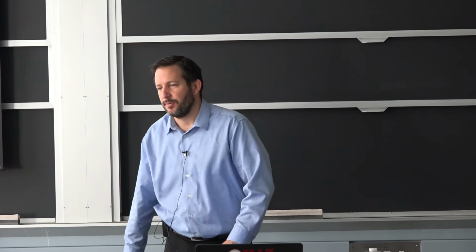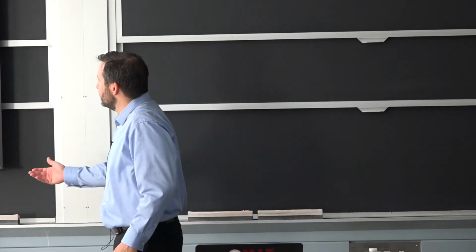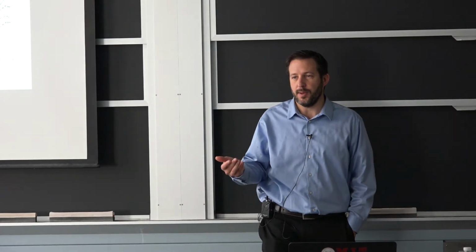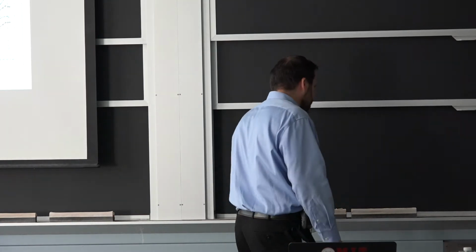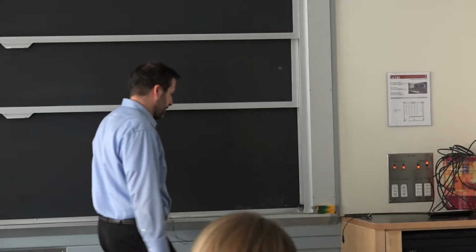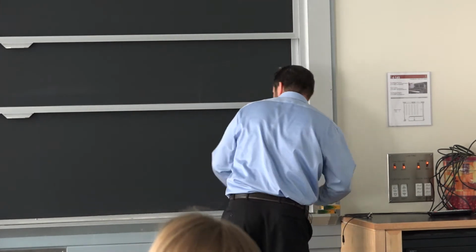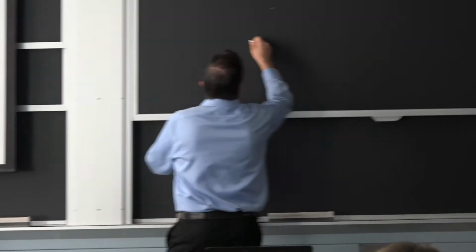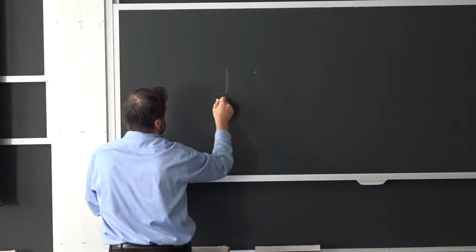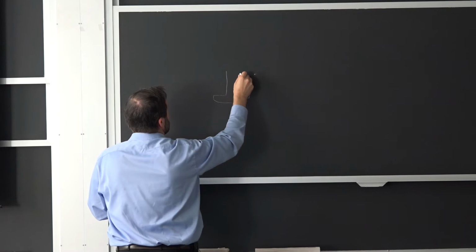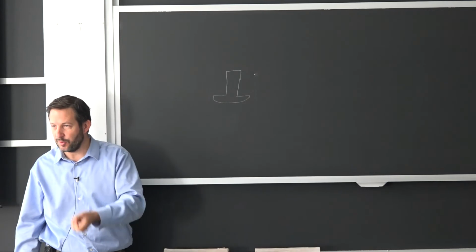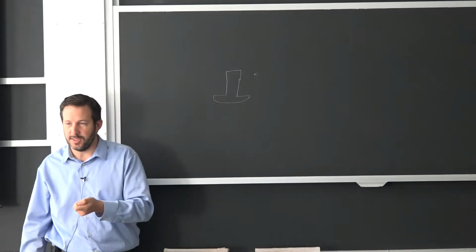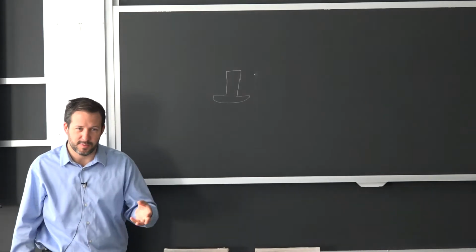There are a few examples, like rivets for aircraft, that do not need to be heated to age. They're a little bit like studs, so we're not talking about pop rivets. We're talking about the real solid rivets. So they look a little bit like this. You have the shaft, and then you have your head, and it's very solid. So you make that piece, you have a bunch of them, you put them in a screen, heat them up, quench it. Then they put it in a freezer, and they have a maximum time they can keep it there.